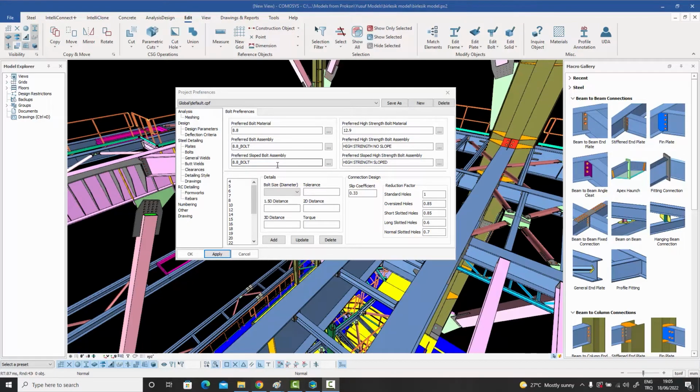So in steel detailing, you have situations where the inner side of the flanges has a slope. A lot of these profiles, for example, like HEA profiles or IPE profiles, have a flat flange on the inner side as well. But some of them, like the UNP, have sloped flanges. And for the sloped flanges, what changes is the standard of the washer. And so you end up using a different assembly for those, and this is one of the most common mistakes in steel detailing, that the detailers end up using the same assembly everywhere, whereas for the sloped flanges they should be using a different bolt assembly.